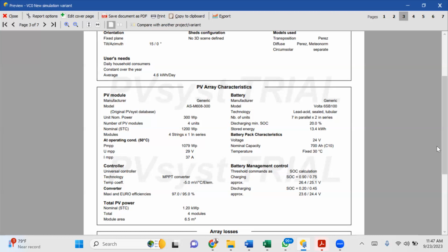The battery is there. The minimum discharging is 20%, so that means DOD is 80. So that's a high efficiency lead acid battery from Volta. I know it's expensive. So unlike what we said, DOD 50%, it's just for you to play safer, right? Because you don't know the maker of your battery. But if you're using a Volta battery, it can guarantee you 80%. But as an engineer, in order to have a higher safety factor, you can reduce it to 60 or 70. Okay.